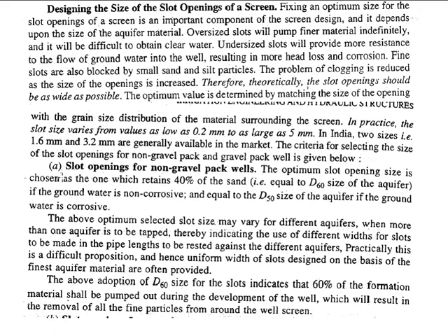So let us first come to the slot opening for the non-gravel pack well. If it is a non-gravel pack, and if we are using a certain packing material at the sides of the well, that should be a non-gravel material. In that case, the optimum slot opening is kept at D60, which means the size of the particle when 60% are allowed to pass and the rest 40% are retained, and that is the case for a non-corrosive case.